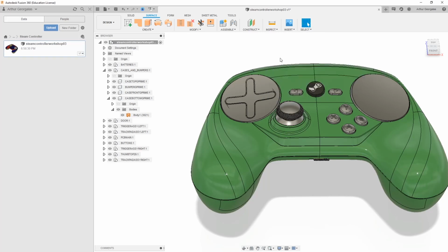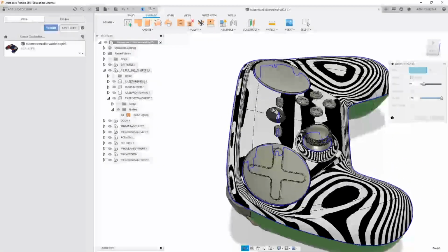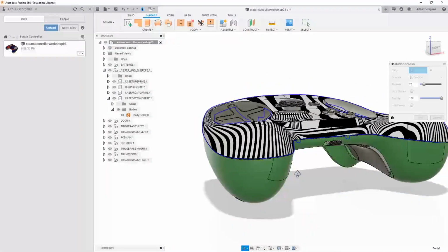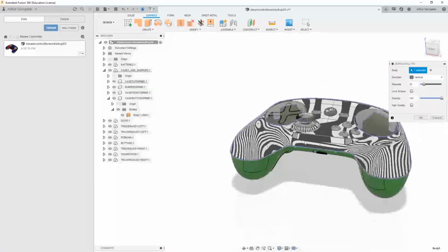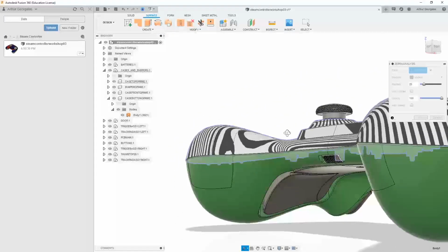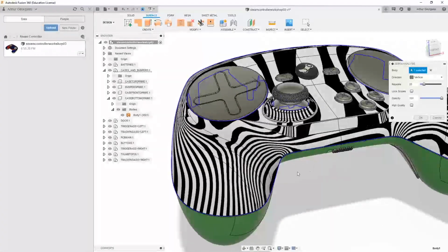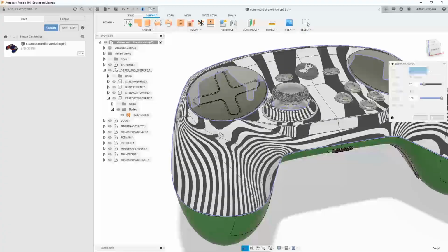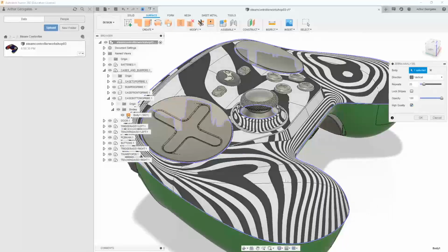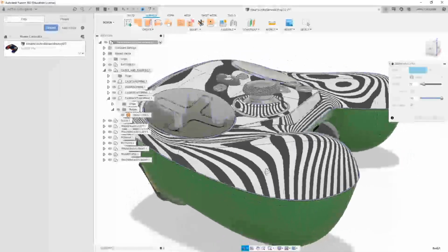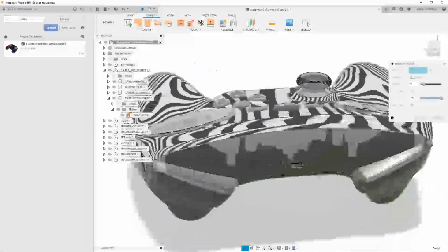We've got the zebra analysis, which you may have seen from SolidWorks, where you can see how these lines transition from surface to surface. And down here, it's absolutely fine that there's a sharp change there because it's going from a smooth surface and then jutting up. What's important is these sections here transition into themselves smoothly, and they're pretty good. This isn't the high quality. When I turn the high quality on, it should look a bit better. And yeah, now those surfaces look much, much smoother. So that's one way of looking at surfaces.